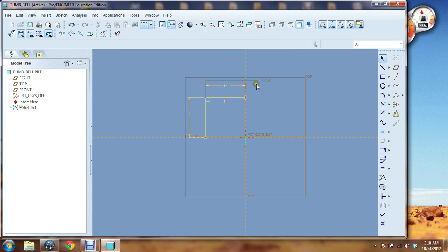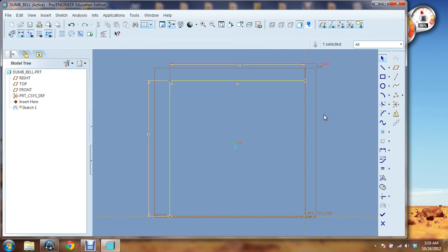And we could actually go ahead and we can still drag this around, and you notice it still does not violate that constraint. Now I don't have as much freedom to move this around. And then we can go ahead and set this dimension just by double clicking it. We'll go ahead and call this 10, and then hit enter. Automatically zooms in for us.